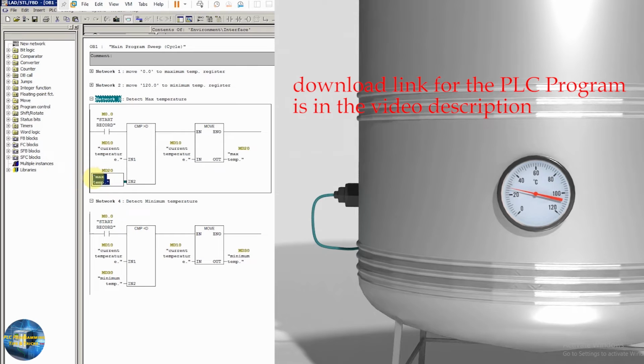After some time, let's suppose that our temperature drops to 18 degrees. What will happen? This 18 degrees is less than the 20 degrees, and this comparison command will stay false, and it will remain 20 degrees as the maximum temperature value in the MD20 data register. Now in network 4, we will detect the minimum temperature.